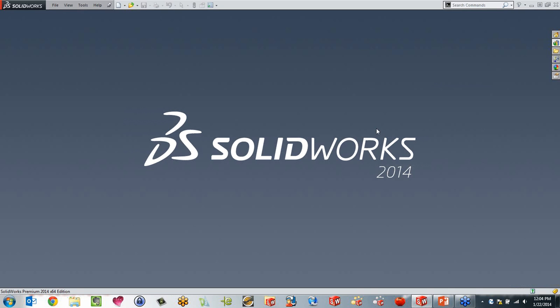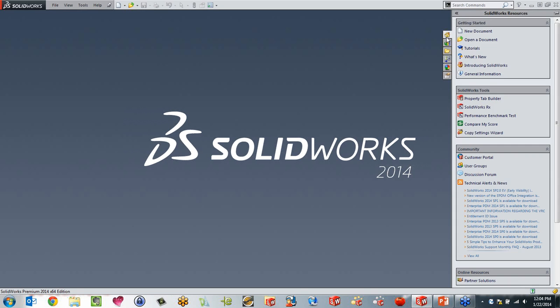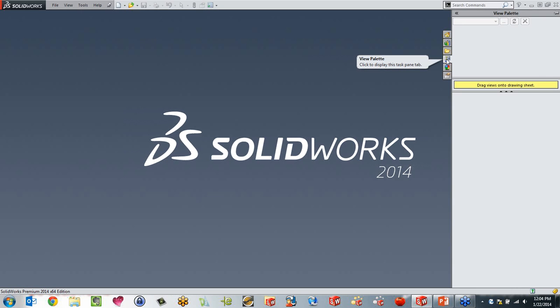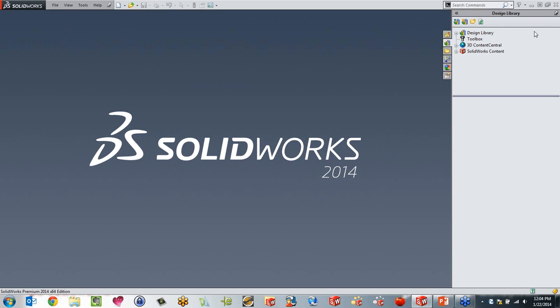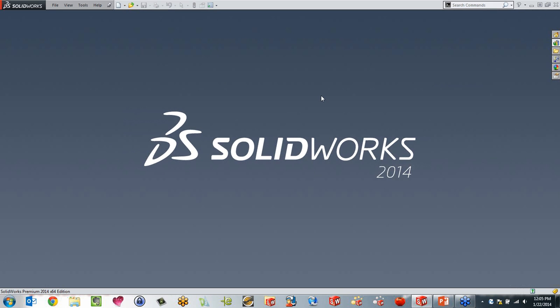So inside SolidWorks, your design library is sitting over here. There's this task pane over here that has some different buttons. If you ever created drawings, you've probably been inside the view palette. And right here are these bookcases, and that is the design library. Now, when you work with it, you can hit this thumb tag up here, and then it will actually stay. If you don't have that, when you click outside, it goes away.